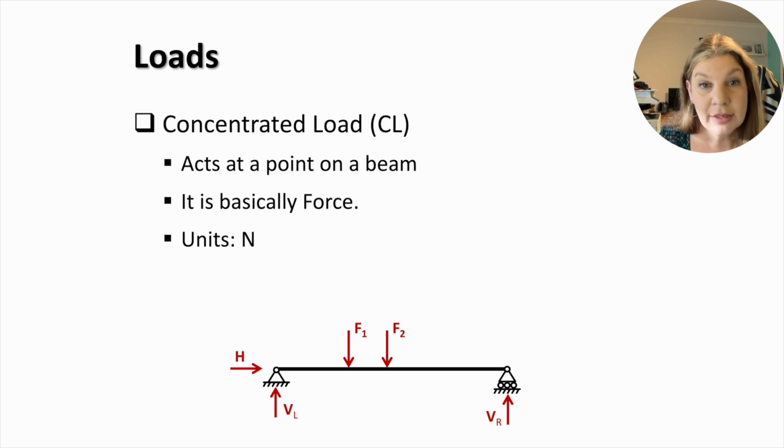The bridge will react to these concentrated loads by developing reactions at the supports. There is a horizontal and a vertical reaction at the left support, or pin support, and a vertical reaction at the right roller or sliding support. The reactions are also concentrated loads.